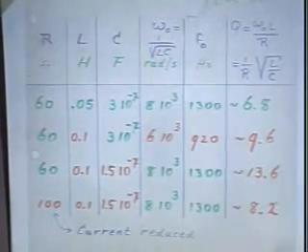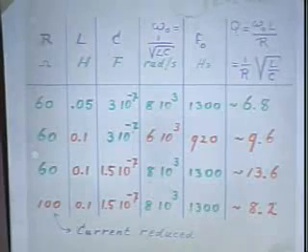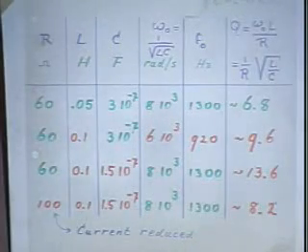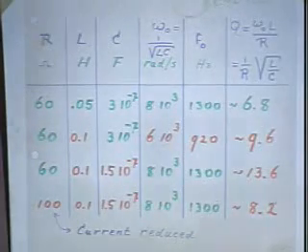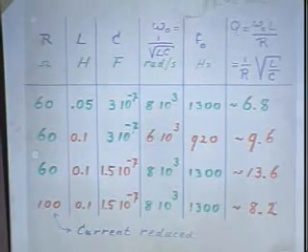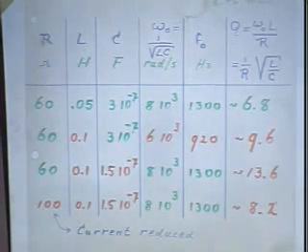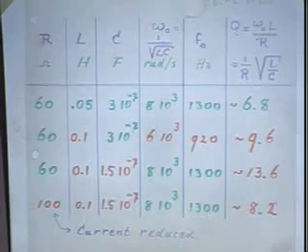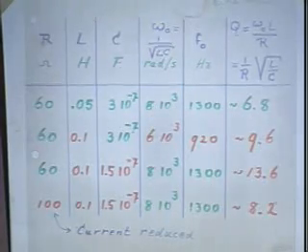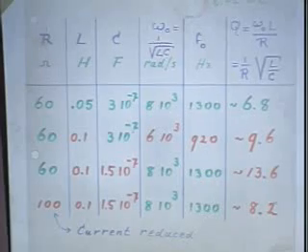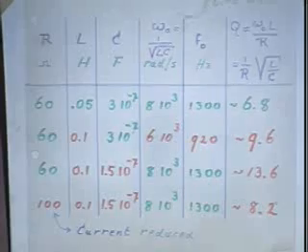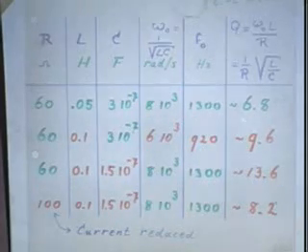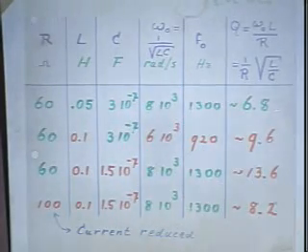And I will change the light setting so that we can also enjoy the demonstration. The idea being that for these values that I have there, in the first line you see R, 60 ohms, and the self-inductance is 50 millihenry, and the capacitance is 0.3 microfarads. So that's a given there. And I give you here the resonance frequency, 8,000, in terms of omega, radians per second. This is the resonance frequency in hertz. And just in case you're interested, I give you the Q value there as well.